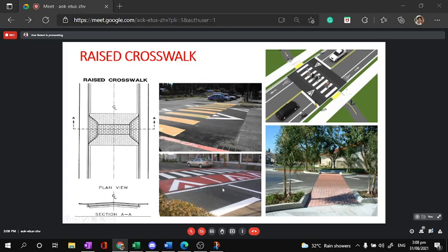Besides elevating, use very vivid pavement marking for yield and crossing. You can also do tiling, brick tile, to really slow down vehicles in that section of the road. That way, pedestrians are safe. So this black section here is actually rubberized or elevated before the actual crossing. And then there are yield signs and stop lines for motorists.